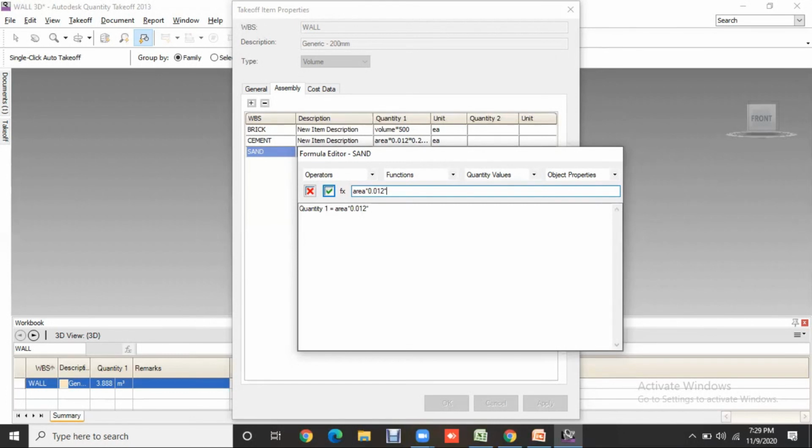So in that case, suppose we have to use 25% cement. The remaining is sand. So how much sand will be applied? That is 0.75, right? And same, we have to multiply. And suppose 40% is the wastage of sand. So we have to calculate 1.4, right?